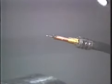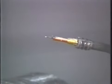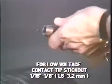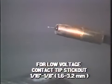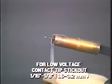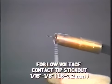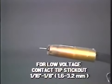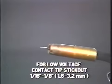And having those extra 1 or 2 volts every time the wire short circuits, the arc becomes a little less stable. So the critical thing on short circuit welding is to keep the contact tip about 1/8 of an inch outside the nozzle, and the wire stick-out about 3/16 of an inch from the end of the contact tip.